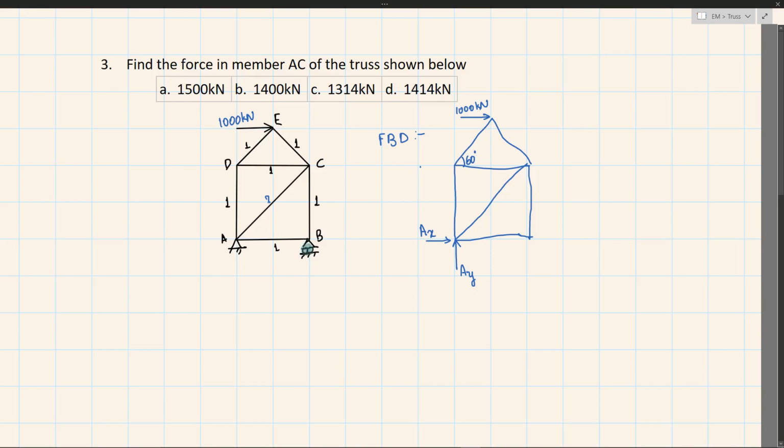Here this is a roller support, right? So this restricts the body to move in the vertical direction. The body is free to move in this direction but not in this. So there will be only reactive forces in the vertical direction wherever we have a roller joint. So only BY. There will be no horizontal component.